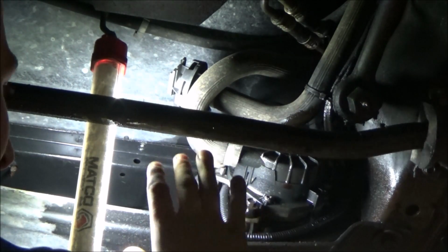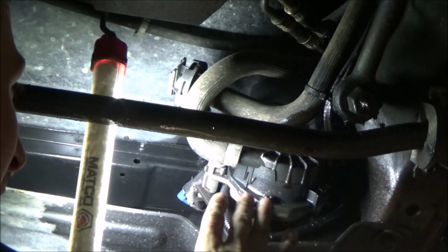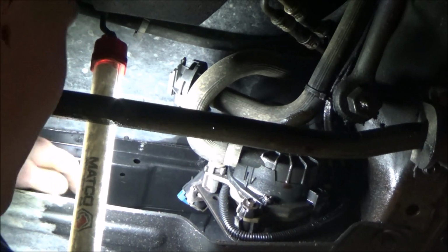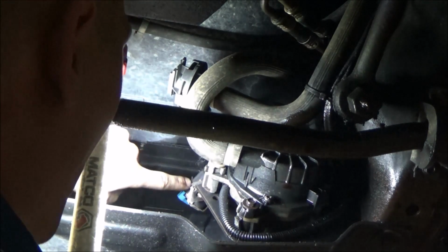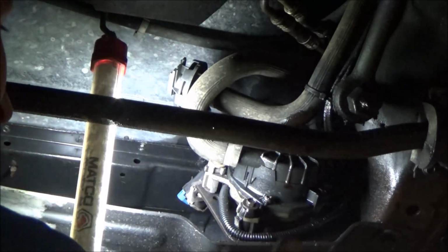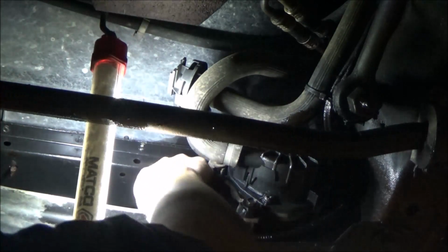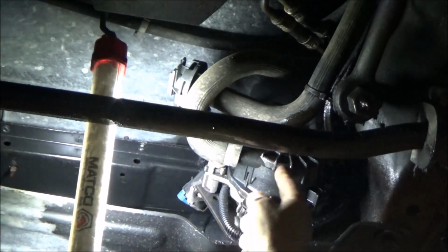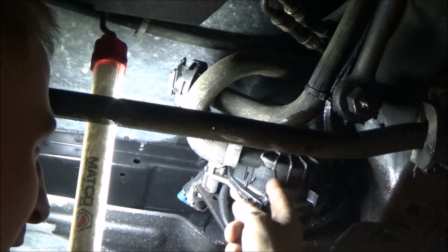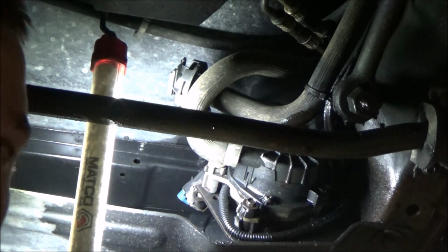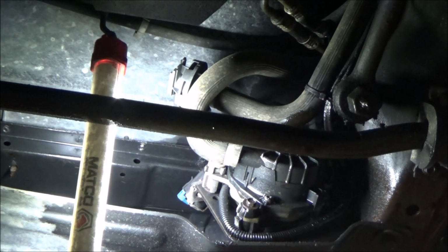So really, I think as for a next step, we need to get a test light here, and we need to look for control on this solenoid at this point. We really need to be worried about this relay, given the fact that this solenoid is not clicking and our motor is not running, which is covered in ATF. So as you guys can see, I don't know if you guys can see that or not. But I'm just going to grab a test light here, guys, and I'm going to use a different test light than we've been using.